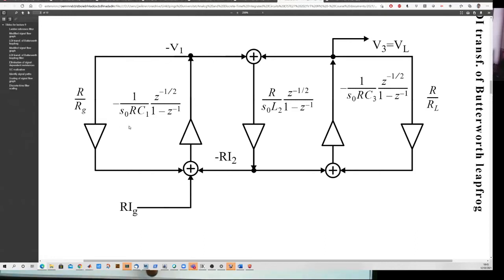And then we replace S with this Z to the minus half thingy. So we're quite close to the accumulator expressions we had from the first hour or in last lecture, but we find a half in the numerator. So we have to get rid of this half somehow. And how do we do that? Well, we take our trick to push a half through the system, flowchart system. So I can imagine I have a half factor in front of this amplifier and I just push it forward or backwards.